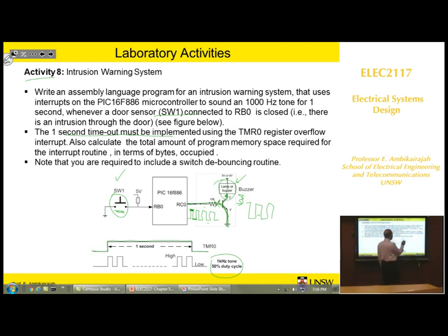You could have a lamp instead of a buzzer. Buzzers sometimes have their own oscillators. You could use a lamp, oscillating and flashing when that happens. And the flashing should occur for 1 second. Also in this program you need to use an interrupt, because as soon as you have your timer output, it should stop. There should be an interrupt service routine as well.